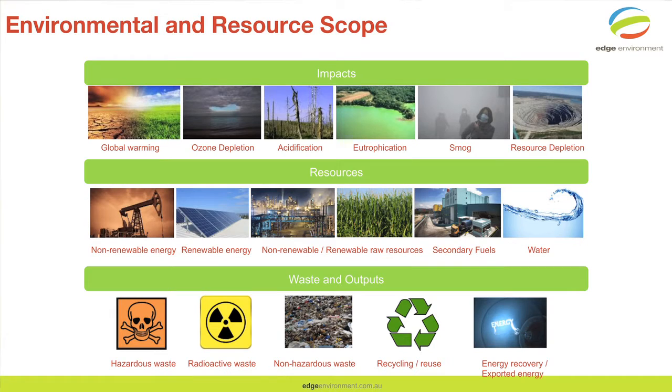What's in a construction product EPD would be a lot of information. It's not really making a statement whether it's a preferable product, like GECA, for example. It gives you the summary of the LCA in terms of your carbon footprint, your water use, how much resources went into making this product, how many of them were renewable, what comes out at the end in terms of hazardous waste, non-hazardous waste, potential for recycling, etc. So you get access to all this information in the EPD.